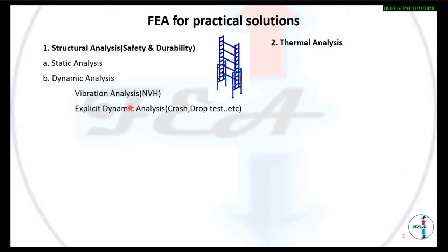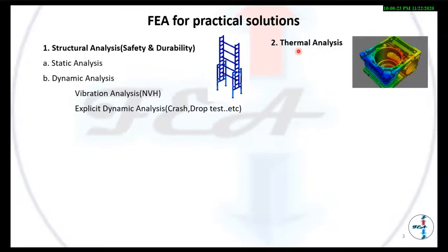In thermal analysis, we are going to deal with heat, only heat transfer. So this is nothing but heat transfer analysis, and heat transfer is nothing but conduction, convection, radiation. All these three phenomena fall into two different categories: steady state as well as transient state. In steady state, the heat transfer rate will not vary with respect to time, but in transient state the heat flow rate will vary with respect to time. We will see more detail about this thermal analysis later.